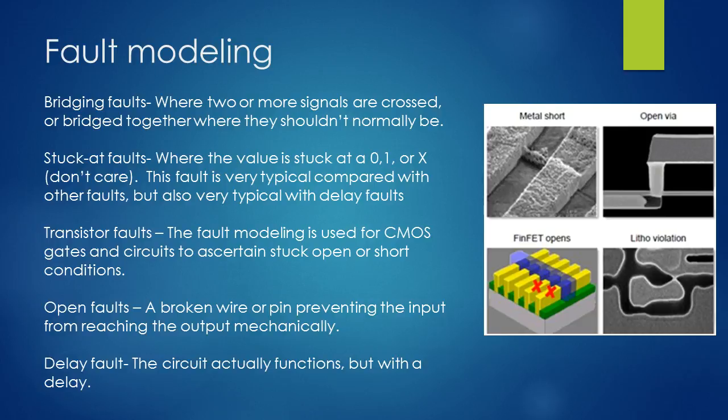The delay fault: the circuit actually functions, but with an inherent delay. This delay can be in a variety of configurations, whether in nanoseconds or even longer. Where the circuit frequency should be operating quicker, it actually operates slower. A majority of my paper actually focuses on delay faults as well as the stuck-at fault conditions, because they are more prevalent.